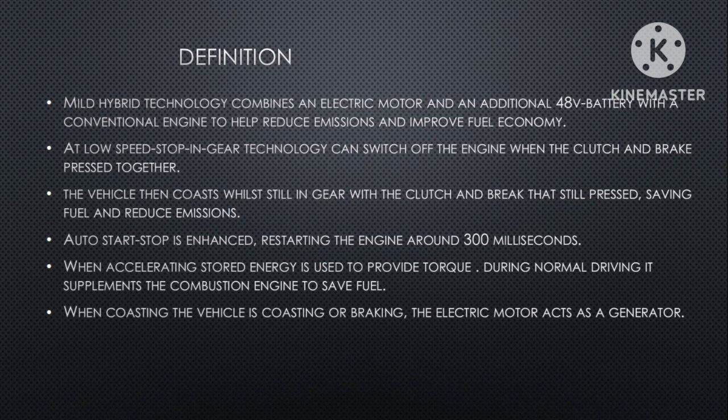The HVAC system is almost the same as in other vehicles, but the evaporator and the condenser of these vehicles are bigger than the normal types. When the engine is stopped and not working, the pistons are not rotating, so they have to store more air inside at the time when the engine is not working, because if the engine is not working, the compressor can't compress the air. That's why they have a bigger evaporator and bigger condenser.